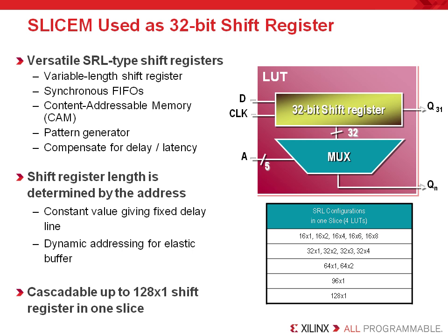The most challenging thing with this is that most customers don't realize that this shift register LUT is not loadable, has no reset, and only offers serial in, serial out capabilities. So if you try to infer it with any of the corresponding behavioral code, your synthesis tool will infer regular registers, and that will be a big waste since you probably want to save the flip-flops for your application.